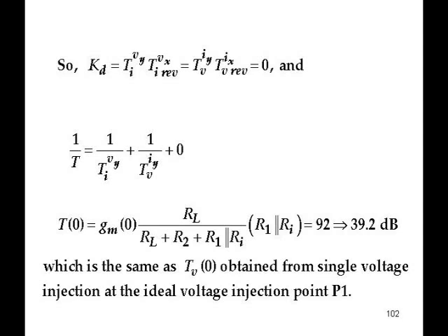That's why the collector base transition layer capacitance of a bipolar transistor always gets into the act, and the corresponding drain gate capacitance for an FET. Those elements are never zero in a real model, and they often control the entire response. So it's important to be able to include them in the result.